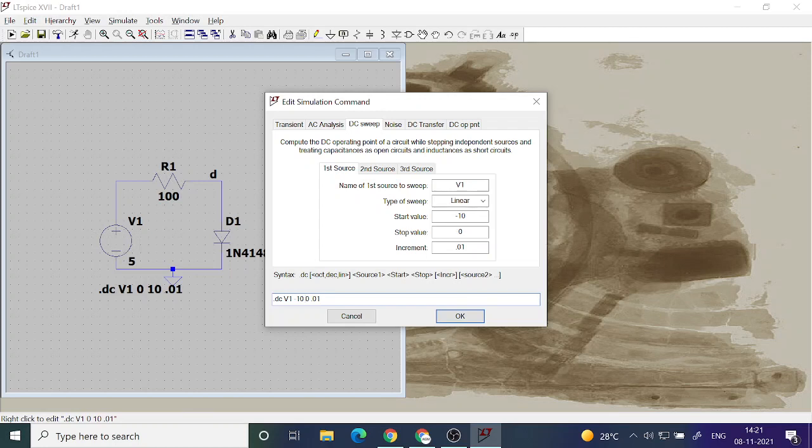In the forward bias we had a current up to 90 milliampere. Now let's see how the current varies when you reverse the polarity of this voltage source. Reversing the polarity of voltage means, when I say minus 10, the signs of the voltage source are effectively made opposite. That means minus is on the upper part, plus on the lower part. Alternatively, you can change the direction of the voltage source. You can rotate it and put it. That is how we can do it in the lab.